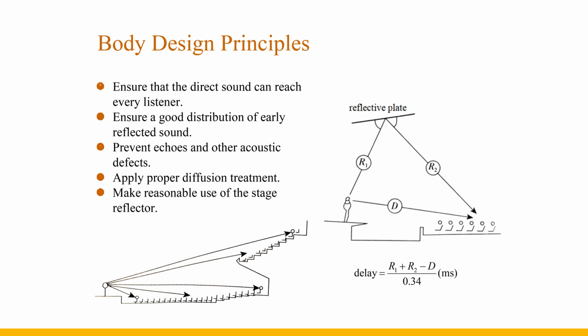Item 1 needs to prevent listeners at the front from obscuring the listeners at the back. Small halls can be equipped with a podium to raise the sound source, and large halls should gradually raise the ground from front to back. Since the wavelength of the sound wave is not shorter than that of the height wave, the propagation requires the wave front to have a sufficient width, so the ground needs to be higher than the height required by the line of sight.